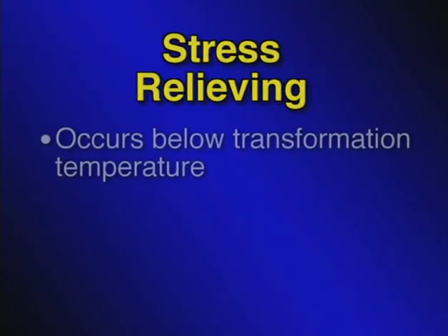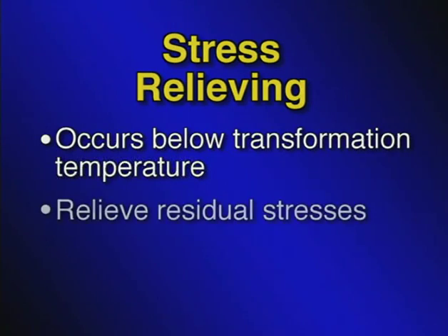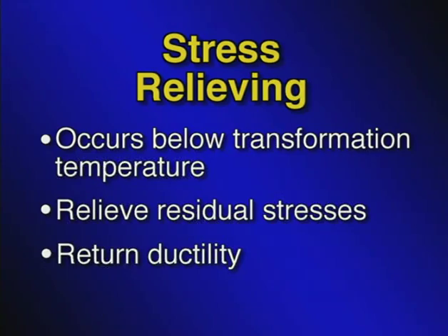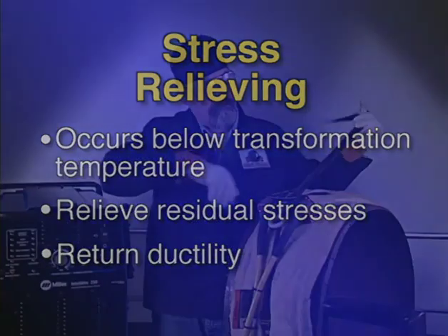Stress relieving takes place below the transformation temperature. It's used primarily to relieve residual stresses from welding and to return ductility to the weld and to the heat-affected zone.